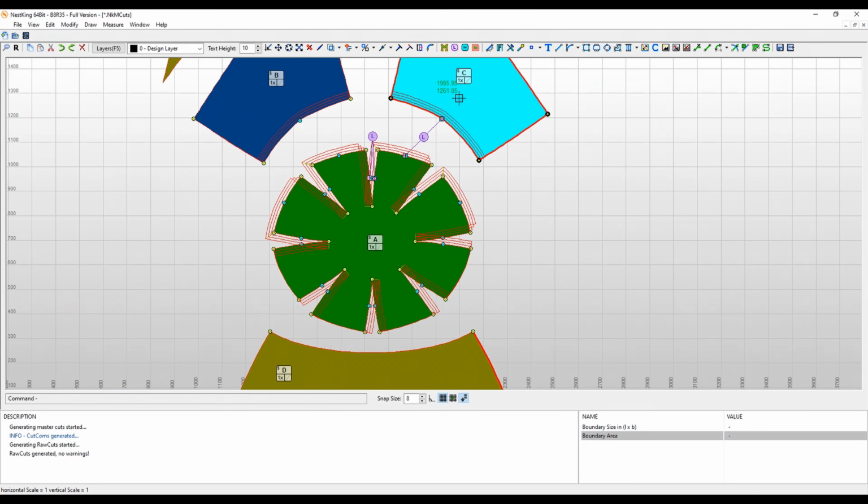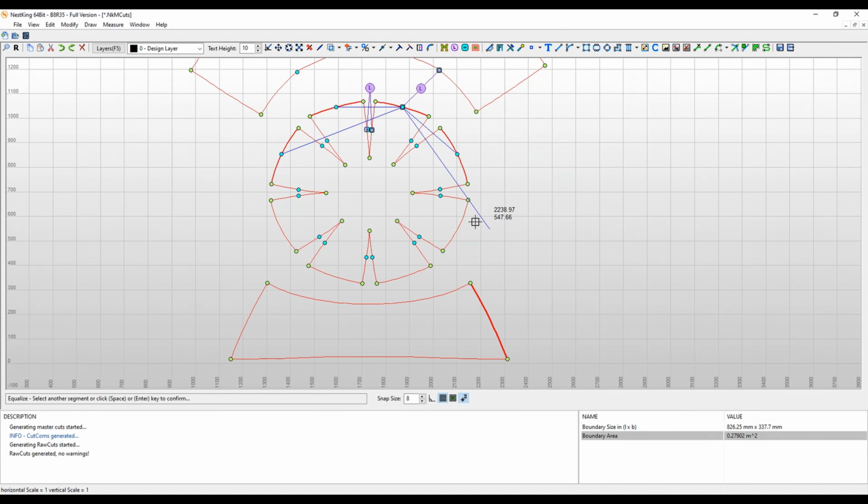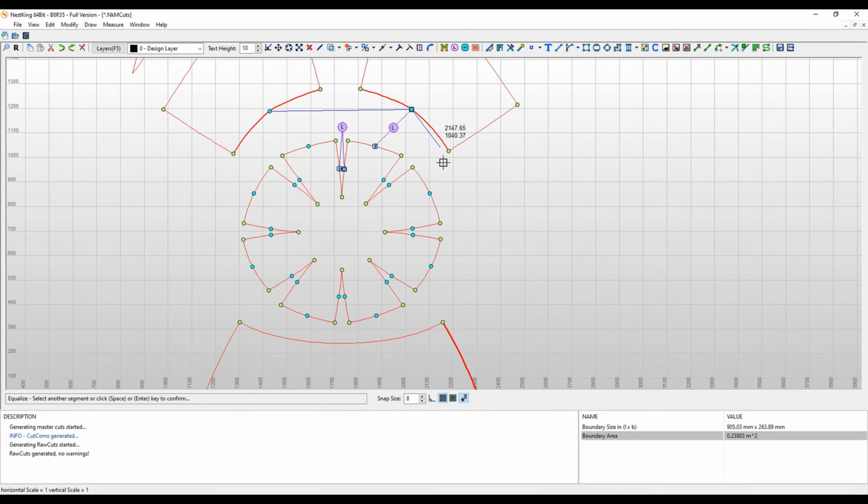And now what I can do, I can either use this, it will automatically select the master and it identifies which is following. So I want this to be transferred to the bottom section as well. And you can again take the linker, mark this. This one is now linked only to the other dark blue section, but I want this to follow as well.